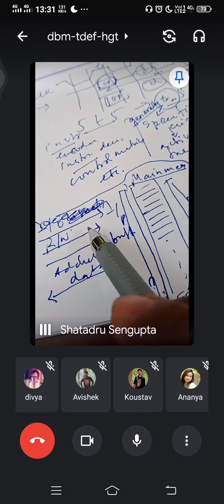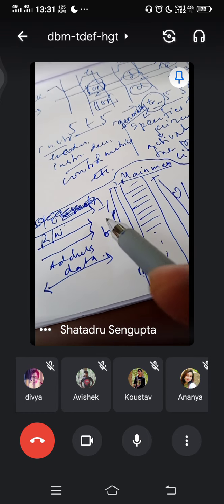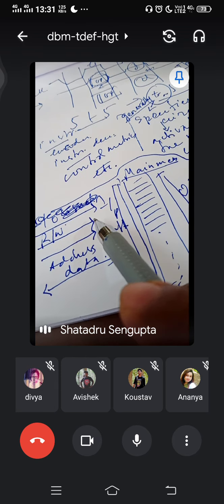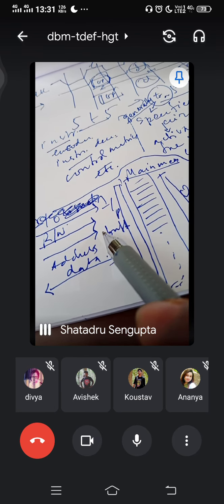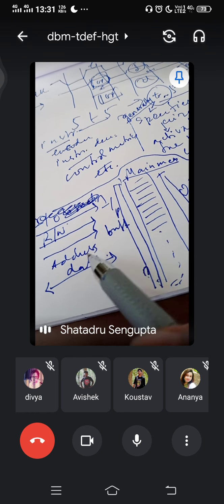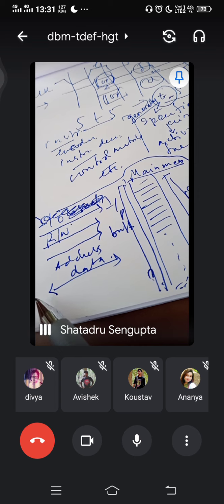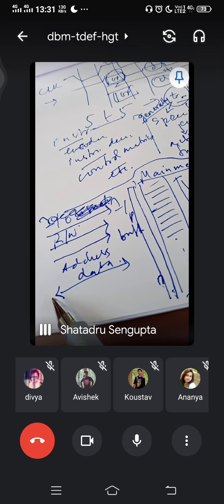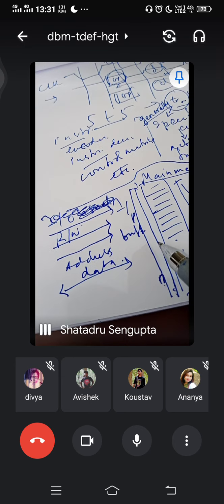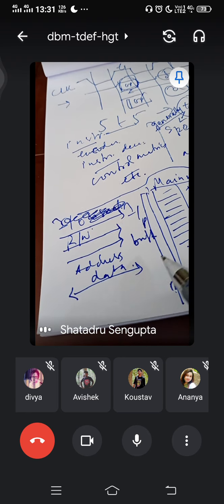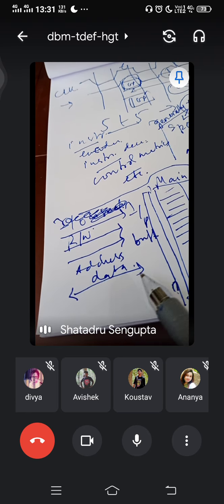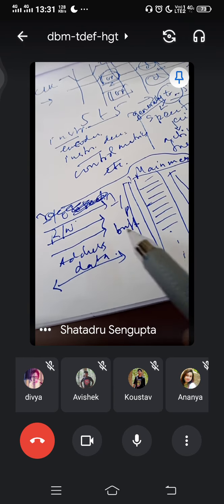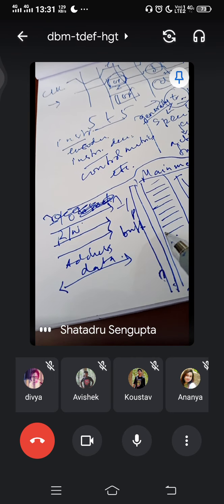If it's on the other hand write, then the output buffer is turned off for the particular address. When write is going on, input buffer is on, output buffer is off. Address comes in, and already the line is selected, and the data that is available in the register or other part of memory. If it flows through the CPU, then it comes from CPU registers. If it comes from memory, then it comes directly from other parts of memory. Whatever is visible in that particular line is copied into the data bus, and it flows into the address that is specified here, and we say it is copied.